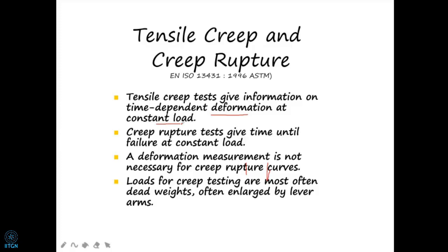Suppose you take a geosynthetic which is pre-tested and apply 100% load. What's going to happen? It will fail instantaneously. It will break, it will rupture. Suppose you apply only 80% of the ultimate tensile strength. Naturally, it may deform and then may fail.